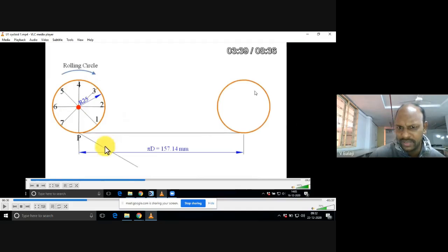If you take fewer equal parts, you get fewer generating points, and while joining the points you will face some problem. That's why taking 8 or 12 divisions is very suitable. Good practice. Now you see how to divide the circle into 8 parts.